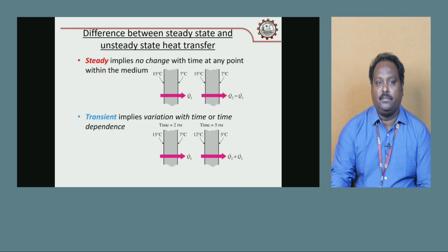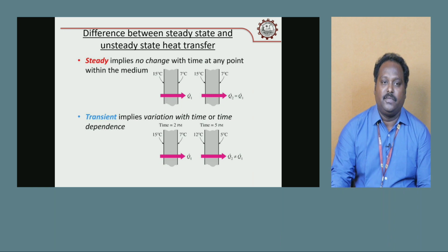Actually, the heat conduction we studied so far is steady state heat conduction. Heat conduction is generally divided into steady state heat conduction and transient heat conduction. So what is the difference between steady state and unsteady state heat conduction? In steady state conduction, heat transfer does not vary with time. The heat transfer can vary only with respect to location.